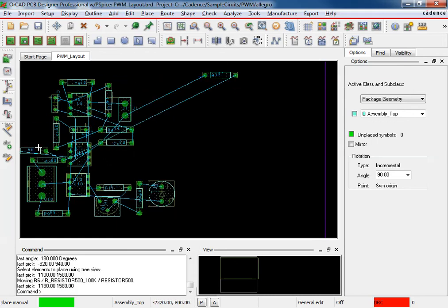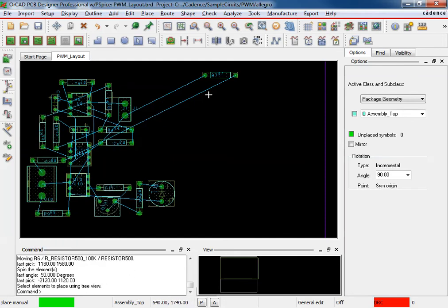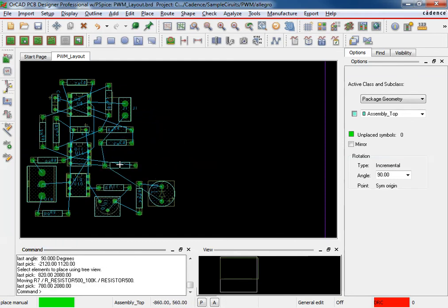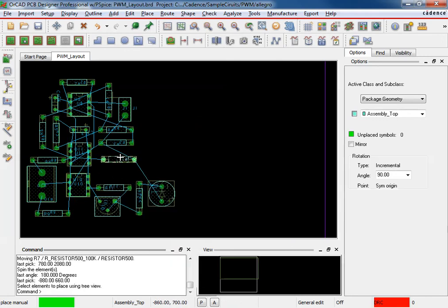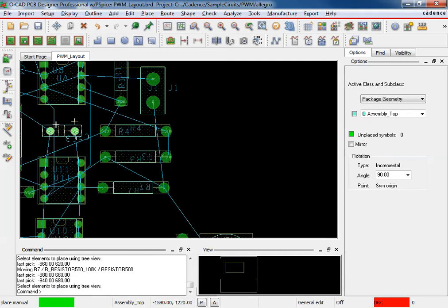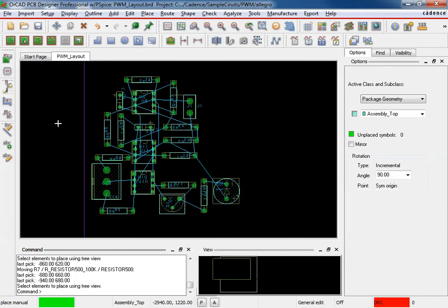And you can actually spend quite a bit of time working on this to get it to be correct. So put it like that. And when I say get it to be correct, have it the fewest number of things crossing. So I'm just going to call this good for now. Is this perfect? I don't know. I don't really care at this point. But you want to keep components together. You don't want to take up a lot of the circuit board. So we're going to have it be here like this for now.